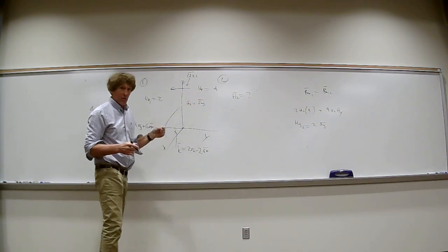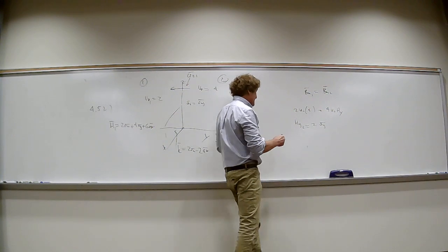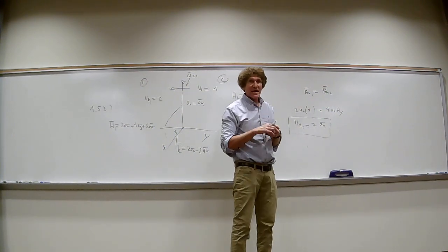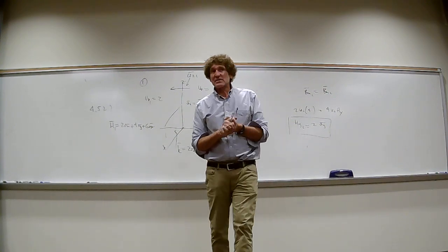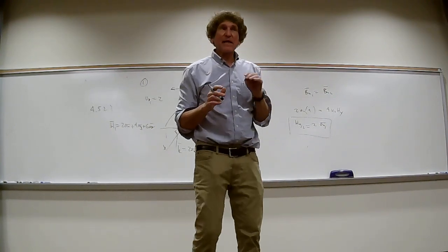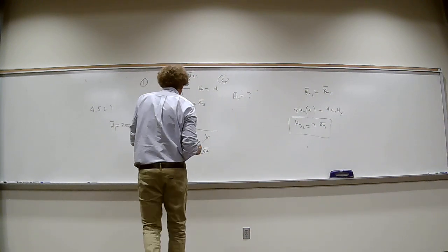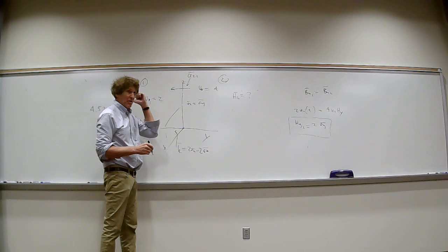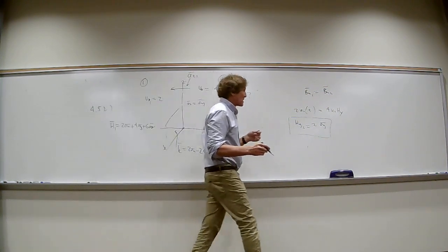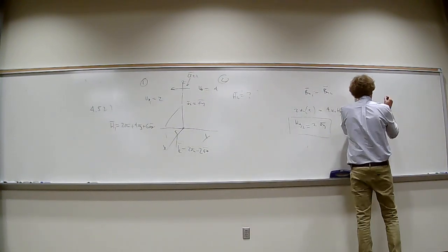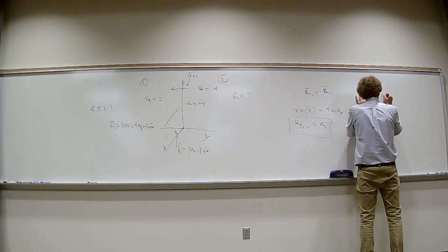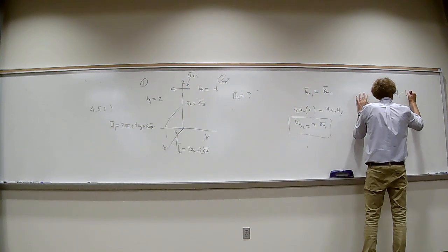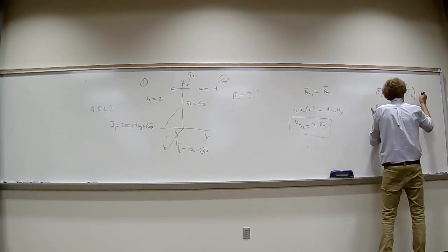That's the right H field, I hope. If you look in there, see if that is the Y component of the H field. It is. All right, now the next part, what he has in his book is a little different than I'm used to seeing, but he has A21 as a unit vector that goes from region 2 towards region 1. Can you all see? And he'll have this form of it: A21 crossed with H1 minus H2, and over here it's going to be K.